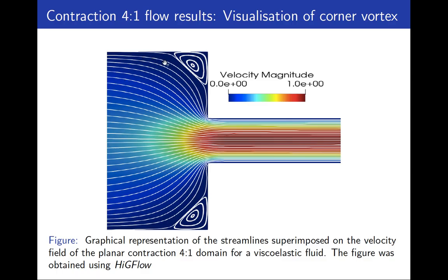But here we have contributions from the velocity in the x direction, because the fluid is moving in this direction, but it is also moving in the y direction. So we also have a contribution from the velocity vector in the y direction. And a streamline can also be seen as a path that is traced out by fluid elements as they move with the flow.